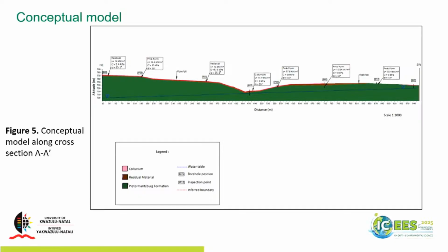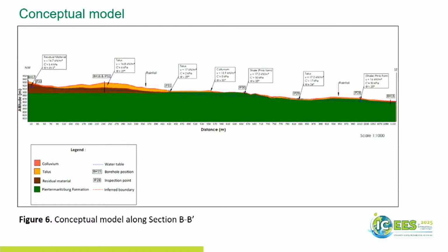So based on the field evidence and all the laboratory reports, we developed a conceptual model of the two cross-sections. This is the first one, along cross-section AA, and this is the second conceptual model based on the borehole data, inspection pits, and laboratory data.